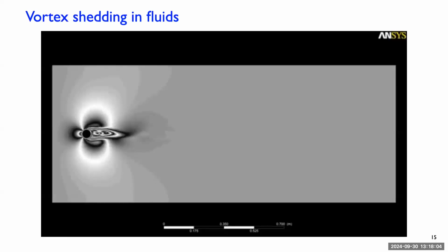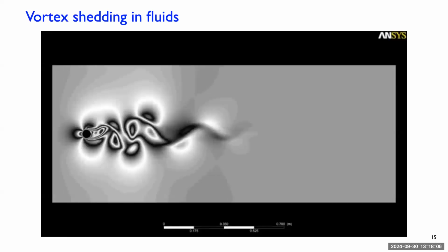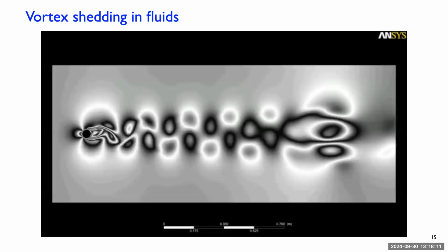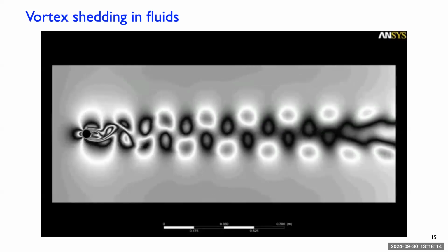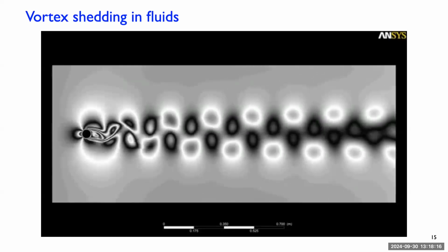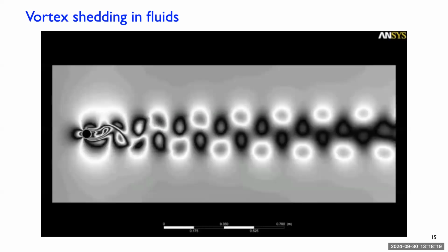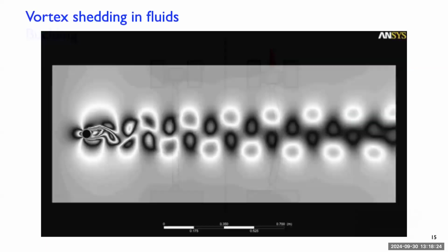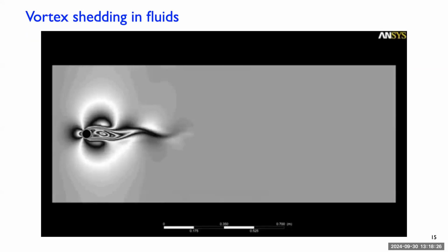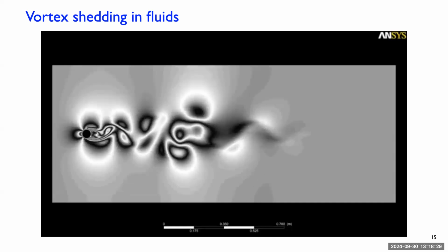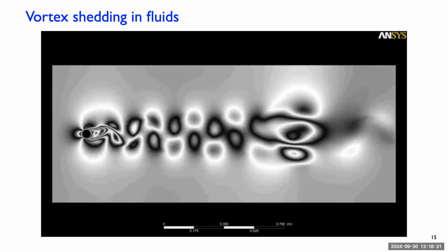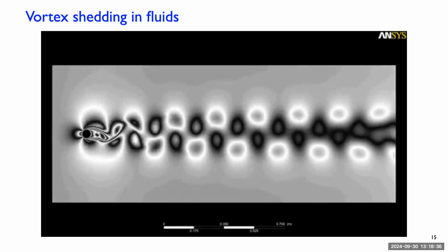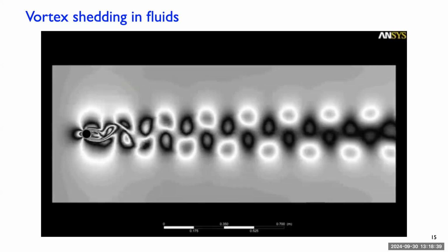And so this is flow around a cylinder. This is one of the problems we're going to look at in the second week of Fluent, whatever week that is, 6. And this is kind of a classic case. As you increase the velocity, holding everything else constant around a cylinder, initially the solution will be symmetric. It broke the symmetry pretty quickly here, but you can set it up so you get these two alternating vortices in the wake that grow longer and longer, but then they become unstable and start flicking off alternating vortices. This is called a von Karman vortex street.